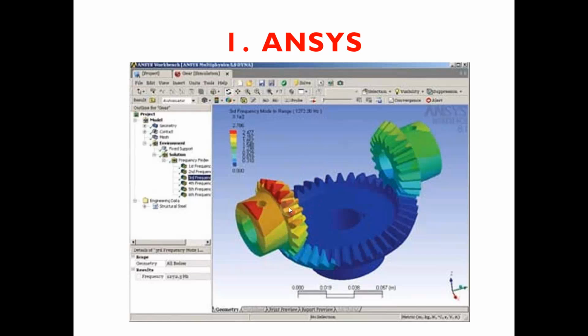it can be heat, or if you are doing any other analysis like fluid flow, it can be any property related to fluid flow. So such color coding will be available in ANSYS or in any analysis software, which gives you information on which areas you need to design well. By looking at this, we can understand the area where the concentration of stress or strain or heat, whatever it is, is more. So you have to give more importance to such areas.